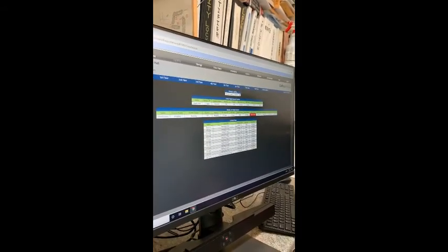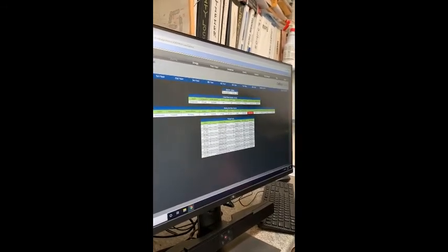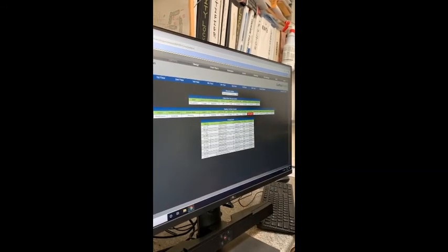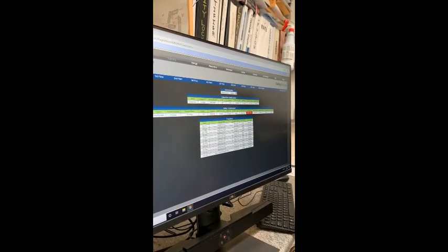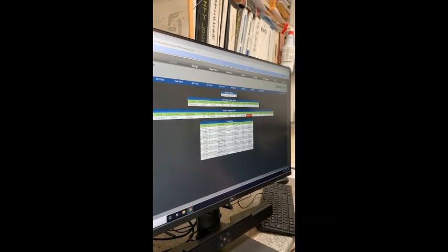What's a JACE? It's a little box. It's basically just a controller. JACE stands for Java Application Computer Environment. These are Distech branded JACEs, so they're technically called an EC Boss 8. They run Niagara N4, which is the 4th version of the Niagara building database system. Would that make it more clear for you?